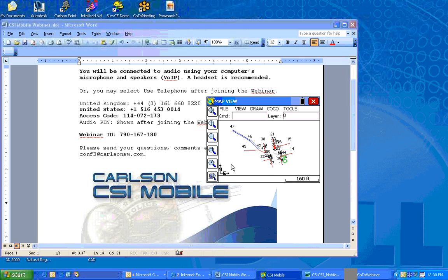And how about that? Just like that, by saying on the first point that you shoot for any line work, if you put OH space and a value, you can create an offset to the right, positive value, or to the left, negative. Now, let's do a rectangle and show you how you could even do a building, if you wanted to, with the vertical part of the building shown.